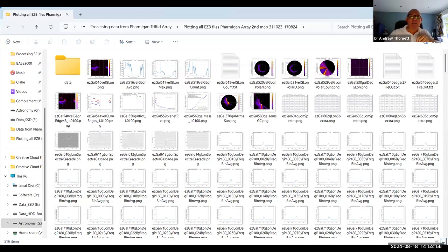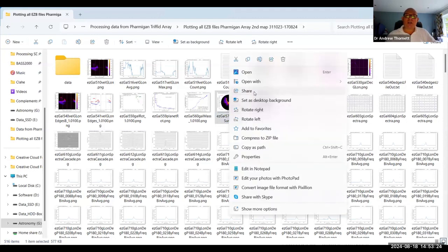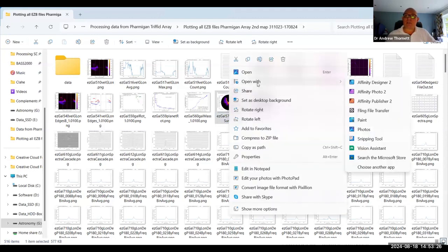It then does have a NooElec SAWbird in the way to actually cut the frequency down to the hydrogen area, and then goes in through a receiver. I forget what I'm using, but it's something like an RTL dongle into the computer where Easy Radio Astronomy does its magic. So I'm going to pull up this latest map that it's produced this time. This is on 550,000 individual data points.